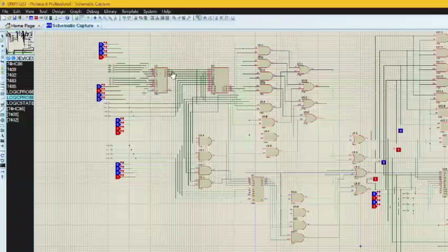So first, the sums go as input of a comparator, and the ladder start is going to the other input. If a is equal to b, it will give us one value, which is ANDed with the sum values, so that if it is 1, it will give me the sum values here. If it is 0, it will give me 0 values here. Now this is taken as another input of a 4-bit binary adder, which adds the ladder length here. So now it will give me another sum value.